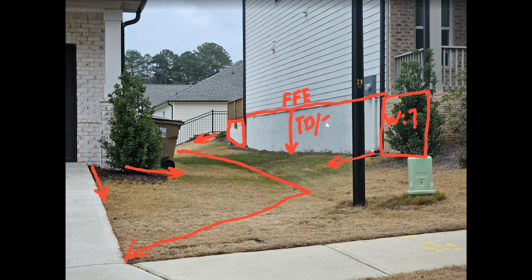For this client here, a turndown is 2.5 feet and lower, and a subwall is 2.5 feet and greater. So with the wing wall back here, basically that is to extend that rear yard. So there's a porch or some type of slab out in the back of the house that wing wall helps to keep that ground level for a little bit so that they can go ahead and have a flat area for that porch or slab that they have back out there.